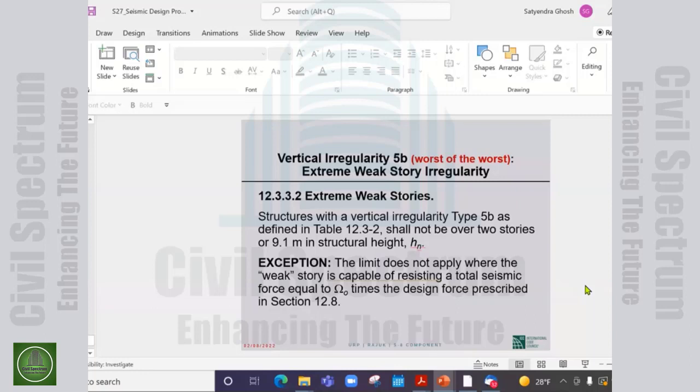If it is a steel column, then it is the steel column, the base plate, the bolts that go into the concrete, but not the concrete foundation. So in other words, the member that is supporting the discontinued structural element, and the entire load path that takes the amplified loading from the transfer girder down to the ground, but not the foundation itself.